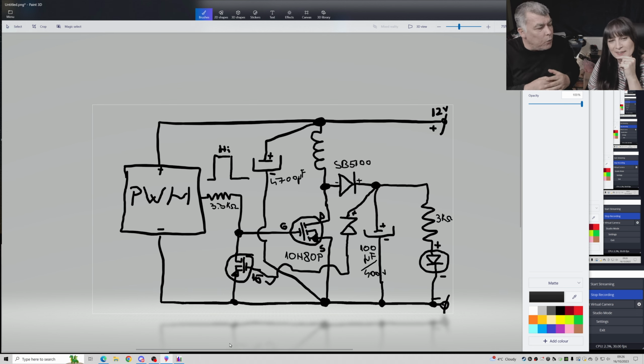You forgot how you use MOSFETs. What did I tell you about MOSFETs? You cannot use the MOSFET as a transistor. The gate always has to be somehow dragged to the ground. Remember I told you the gate is capacitive, and you have to have a resistor between the gate and source.